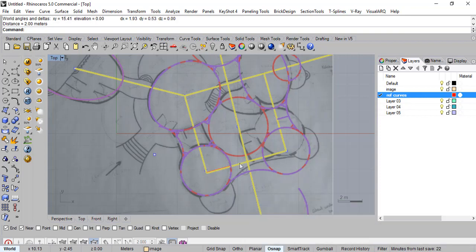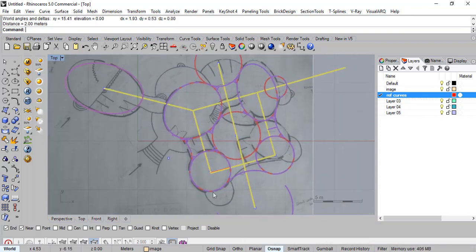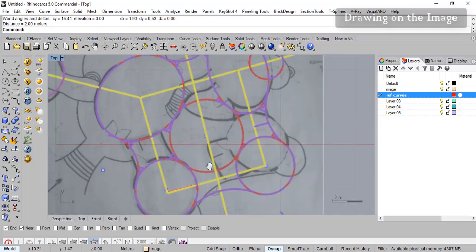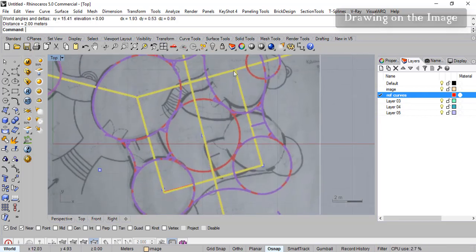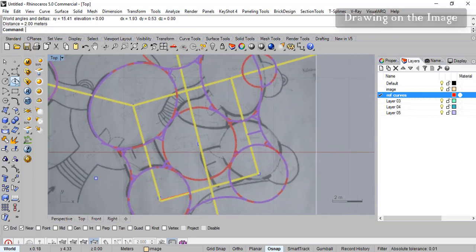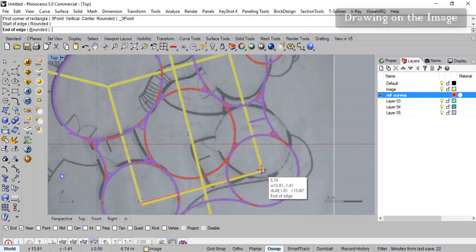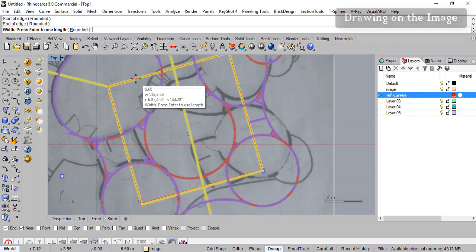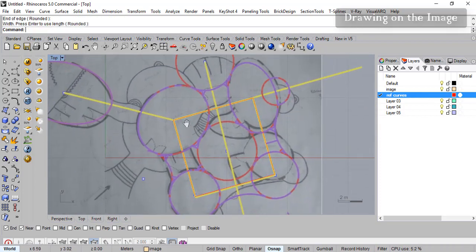Okay, fine. So next what we can do is start building the circles and the ellipses, right? Before that you might want to draw these lines, so you are allowed to do that. Since this rectangle is an inclined rectangle, we can use the third method, where you are required to select 3 points. The first 2 points define one edge of the rectangle, and the third point will define the other edge of the rectangle.